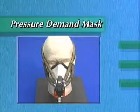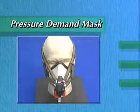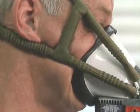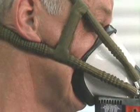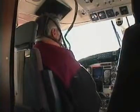The latest generation of oxygen mask is referred to as pressure demand. These masks are designed to create an airtight oxygen seal on the face. The inhalation and exhalation valves are designed to permit oxygen pressure to build up within the face mask, thus supplying oxygen under pressure to the lungs.